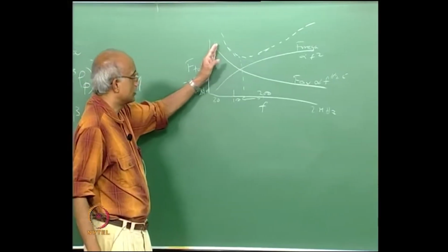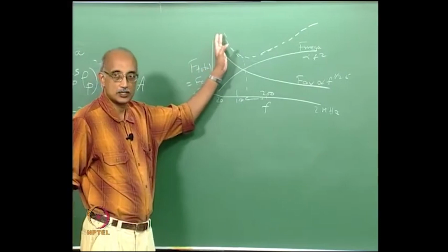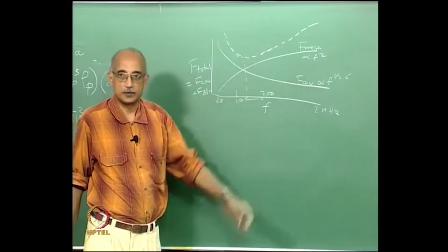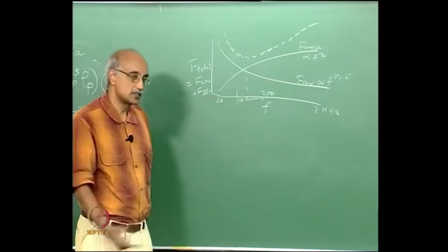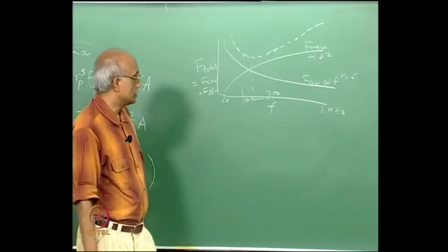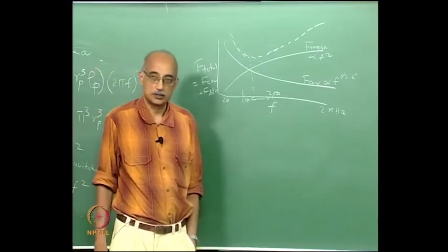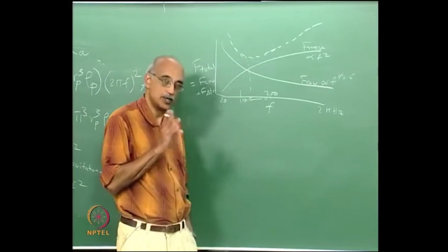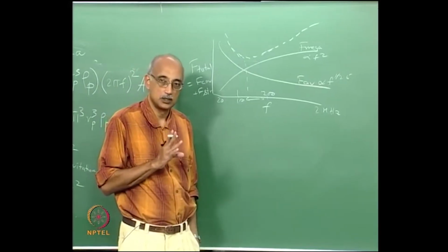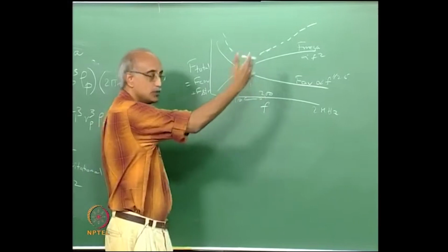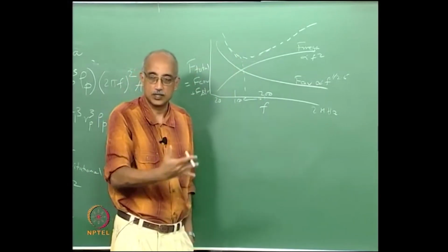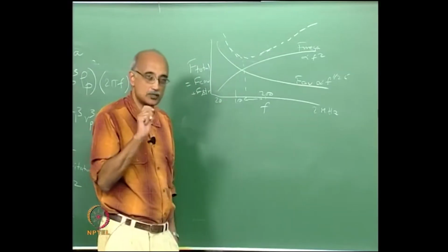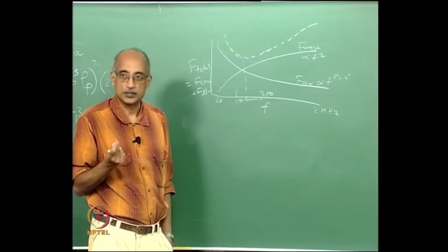If you are on this end, you get high force because of high cavitation. If you are on that end, you get high force because of high megasonic streaming. So, what is the message from this? If you are trying to remove particles from surfaces using acoustic fields, you can actually pick the frequency that you want. By the way, amplitude will simply move these numbers linearly, because amplitude has a linear effect on these forces. So, frequency is where you have the ability to tune your process.